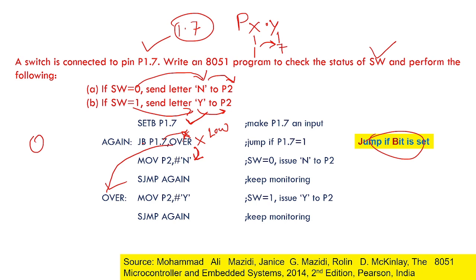Here you need to understand one thing. In the previous programs we sent only numbers, that is, hexadecimal values, but here we are sending a character. Inside the microcontroller the equivalent value will be converted into ASCII and processed by the controller.